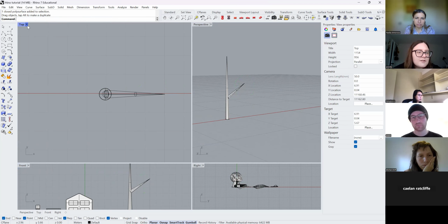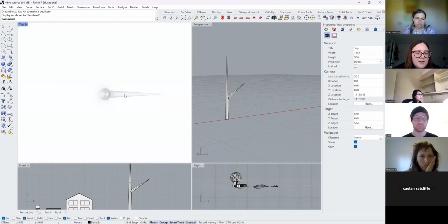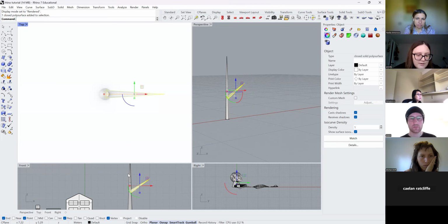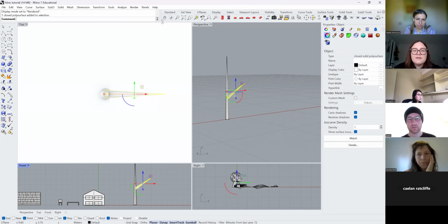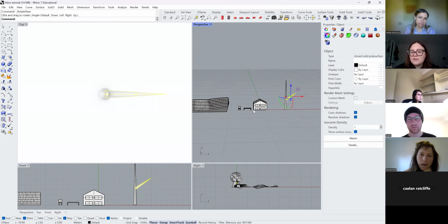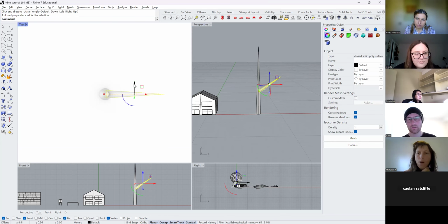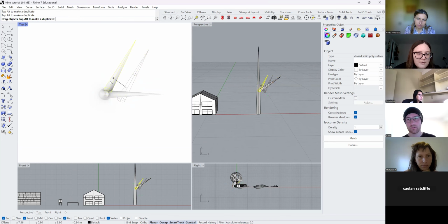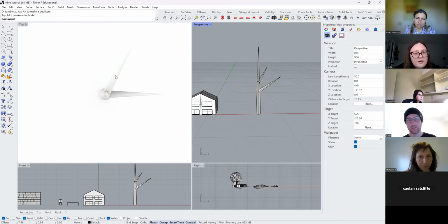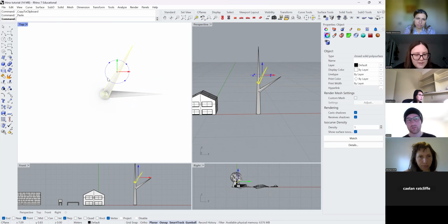So you can see at the top that you've got one of these, and in the front, you can see that it's out to the side, and then if you use your perspective toggle. I'm going to press Alt and then use the gumball, shift this around. And then I want this to not be at the same height, so I'll move it up. Now this isn't going to be perfect, this is just an example.